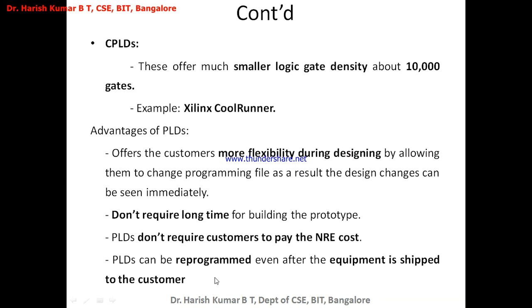So these are some of the important advantages of the PLDs. The first and foremost advantage is flexibility in designing. Any number of times the design can be changed until you get the perfect design, and you don't have to wait for a longer period of time to build an initial prototype. The customer need not pay the non-recurring engineering cost, that is the initial investment, because the design can be done by using programmable logic, and the design can be changed any number of times without additional cost.